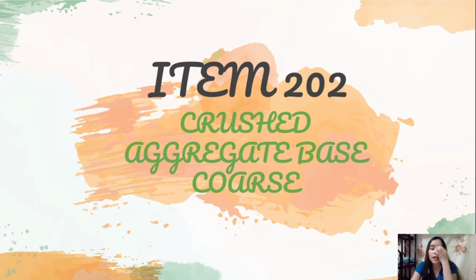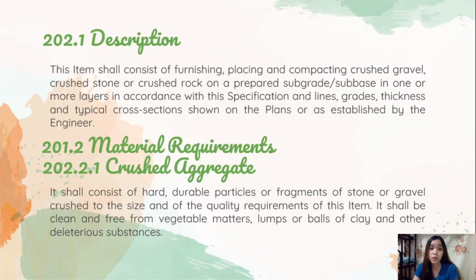Then the unit of measurement is cubic meter. So next is item 202, which is crushed aggregate base course. So the description is, this item shall consist of furnishing, placing and compacting crushed gravel, crushed stone or crushed rock on a prepared subgrade subbase in one or more layers in accordance with the specifications and lines, grades, and thickness and typical cross-section shown on the plans or as established by the engineer.